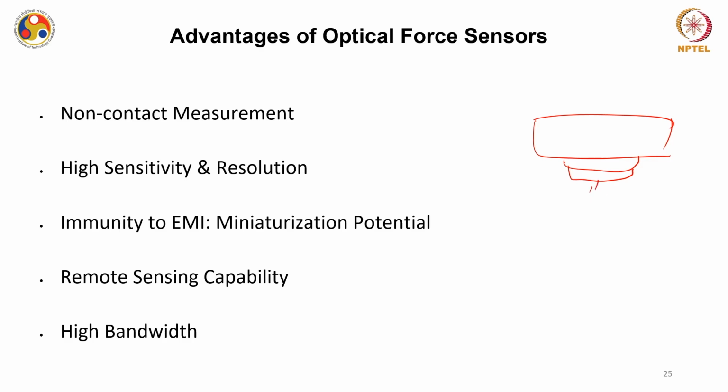Here you do not need any gluing of external force sensing units. You can simply do measurement using non-contact mode. Their sensitivity and resolution is generally higher as compared to strain gauge based devices.